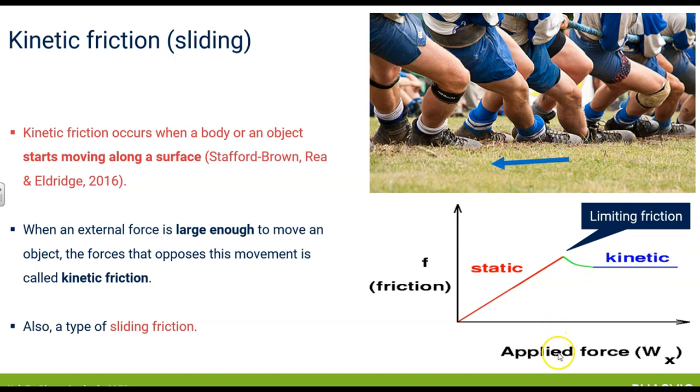left to the right. So if a big enough external force is applied beyond this level that we can overcome that static friction, then we start moving and there will be kinetic friction between the two surfaces. But we revisit this later. Just before we move on, actually, the point at which you reach that amount of external force is called the limiting friction. So beneath that level, there would be static friction. Above that level, there's motion, there's kinetic friction.